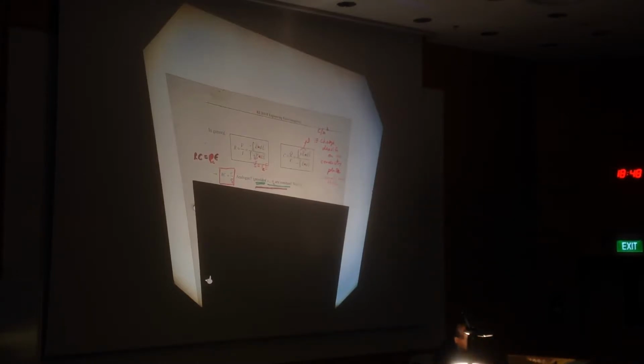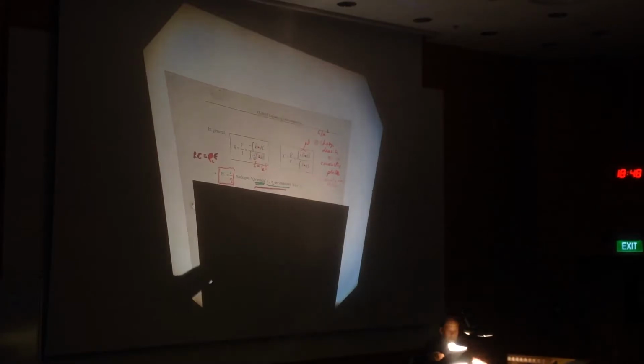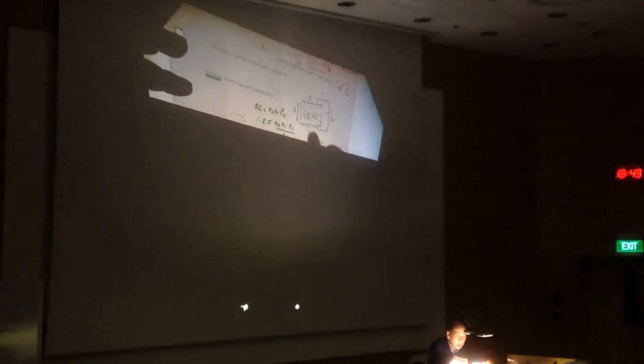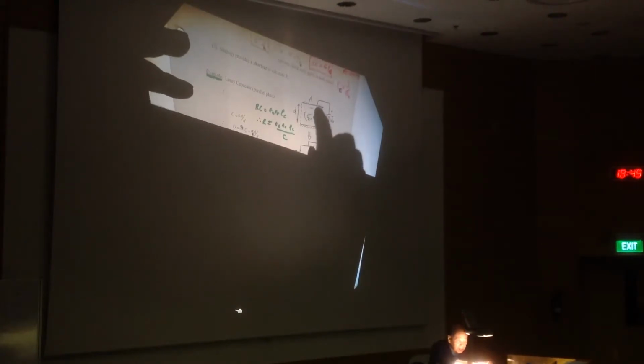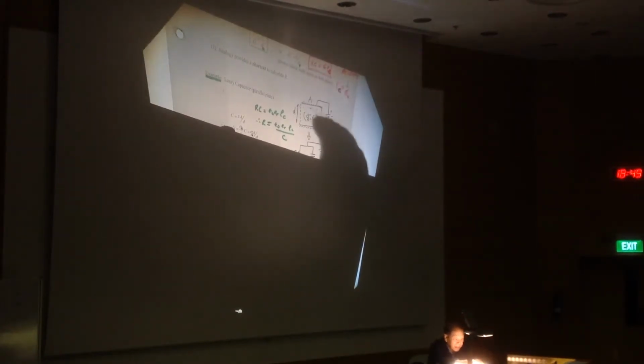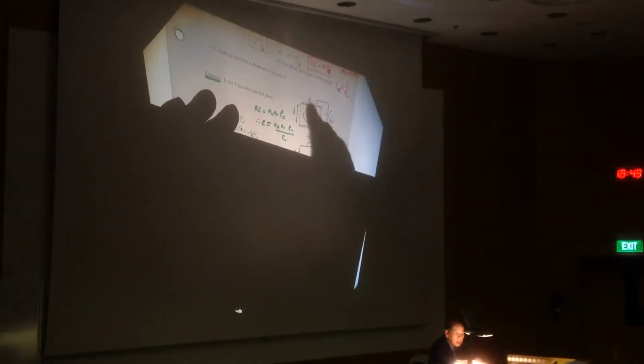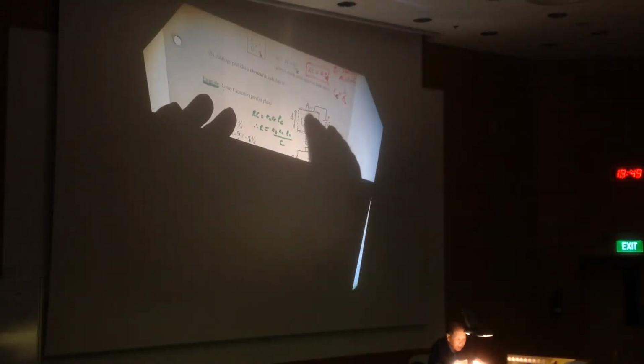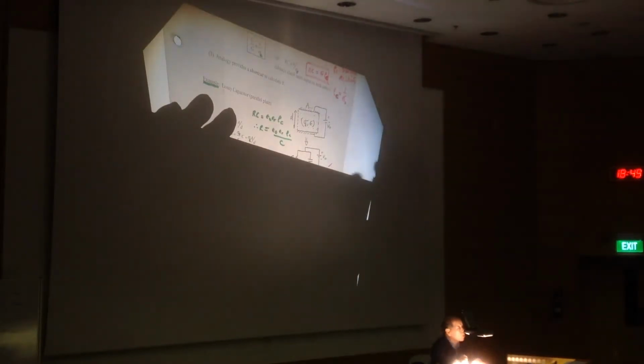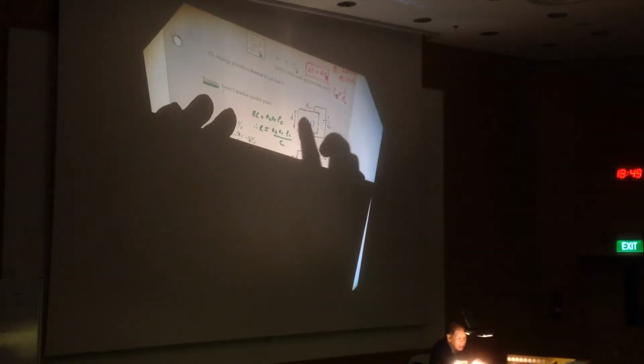For example, I can give you this capacitor here. The capacitor consists of two parallel plates. And the material in between, in the ideal case of the capacitor, the dielectric is perfect, so sigma C will be 0. But now, the dielectric is not perfect, it has a small conductivity.